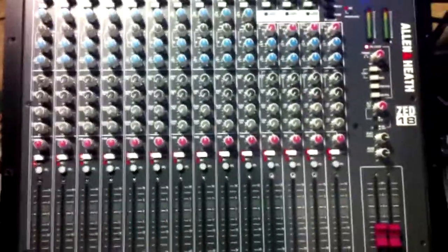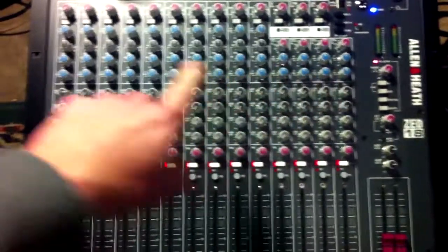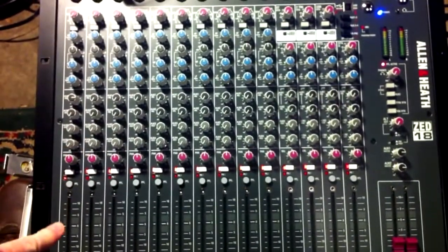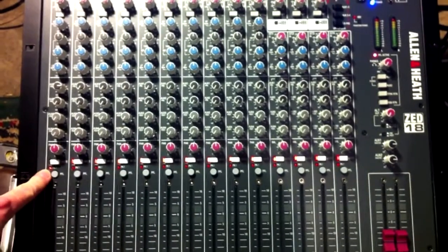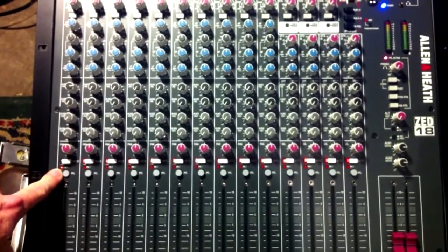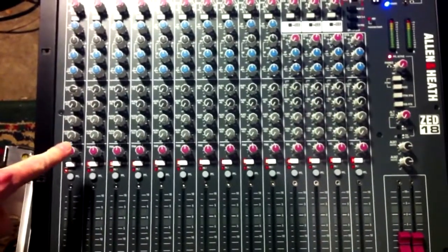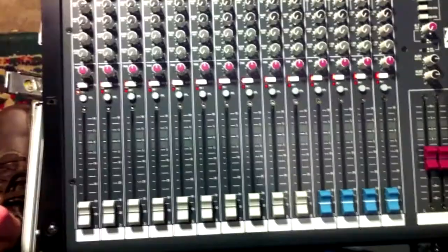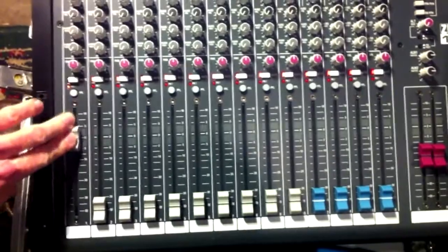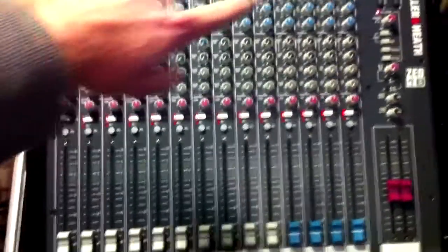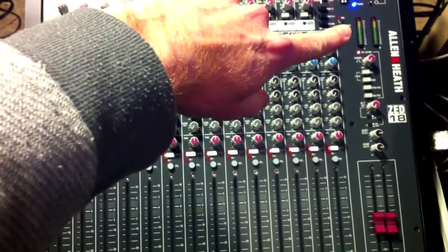When I hit that PFL button, that means that this metering section all the way to the right is now listening to only this channel. So if this light's on, which is our PFL indicator, which most mixers have, that means that this metering section is only going to show this channel. And the level that it's going to show us is pre-fader, so it's not going to matter what level your fader is at. Whatever's coming through before that fader is going to come out right here, both to the headphone jack and to the visual metering.